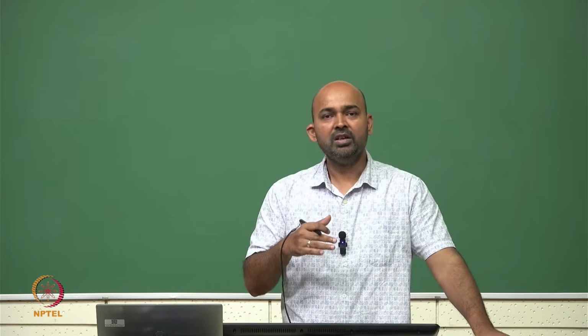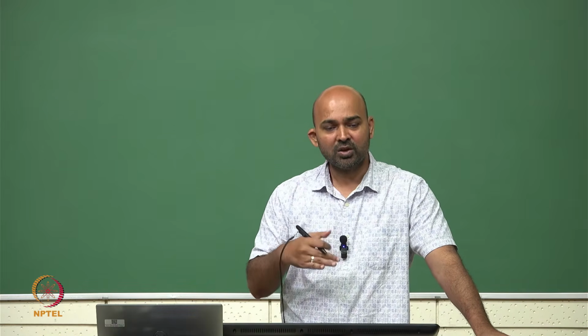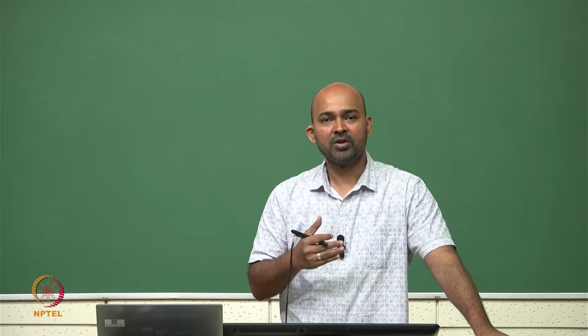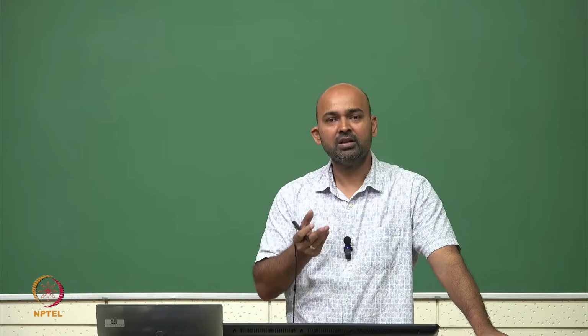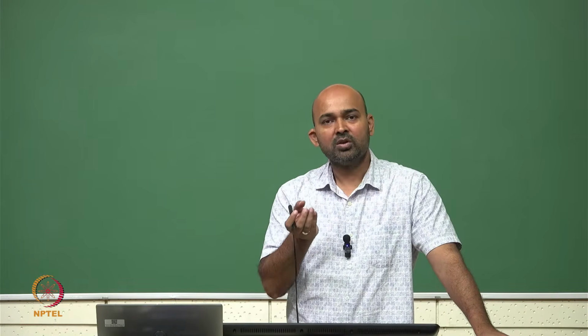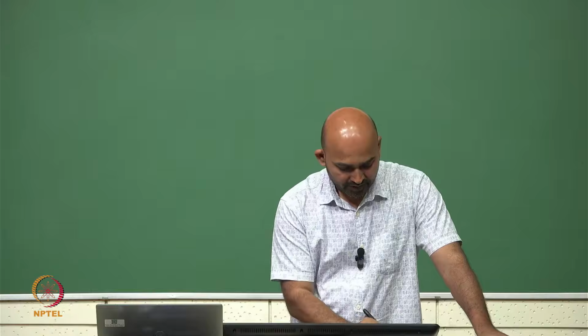So, instead of a complete open circuit, it will be replaced by that very high resistance. This is how SPICE simulates the operating point analysis, or finds the operating point of the circuit. So, we have the DC operating point of SPICE simulation.